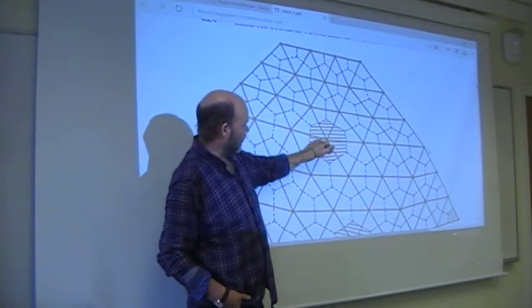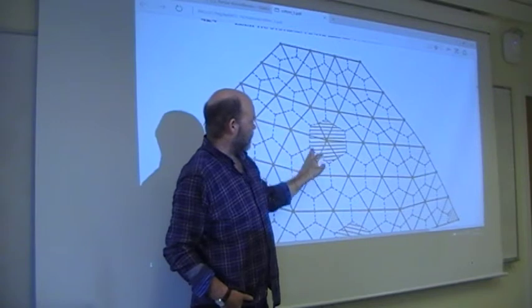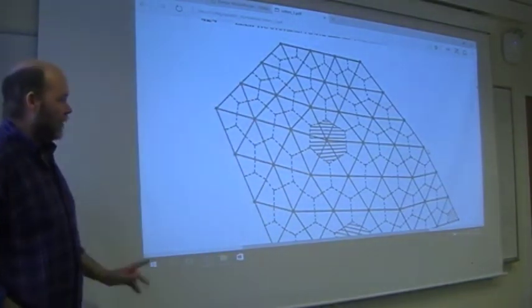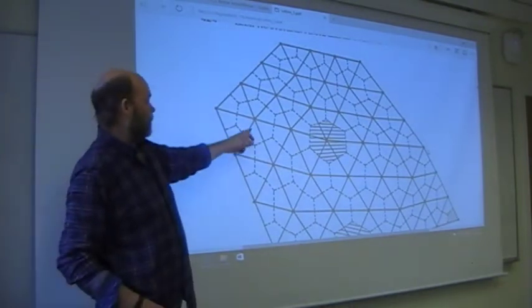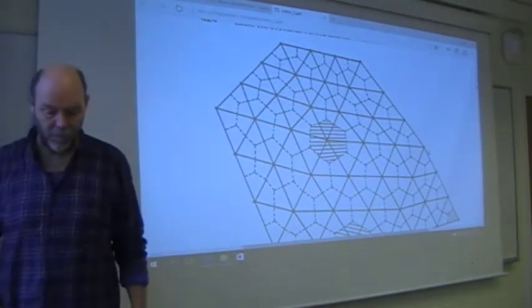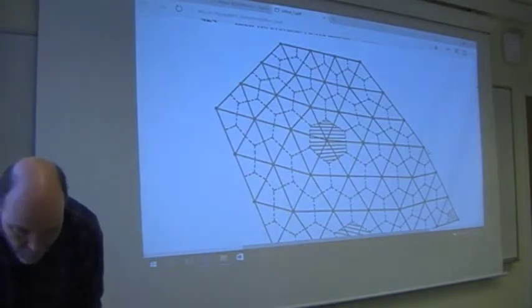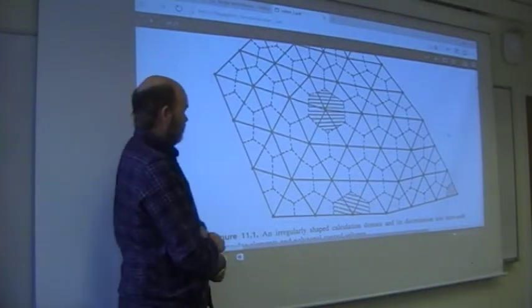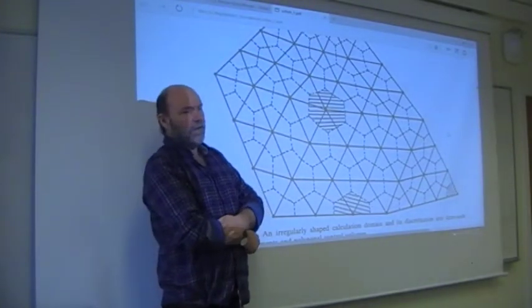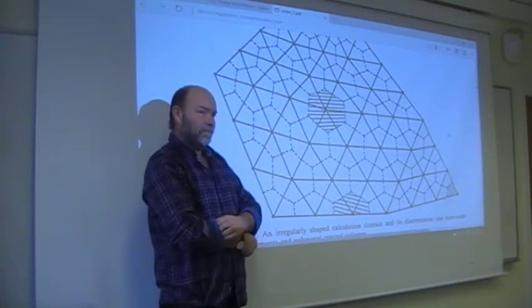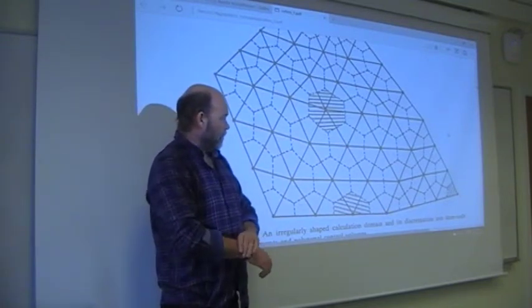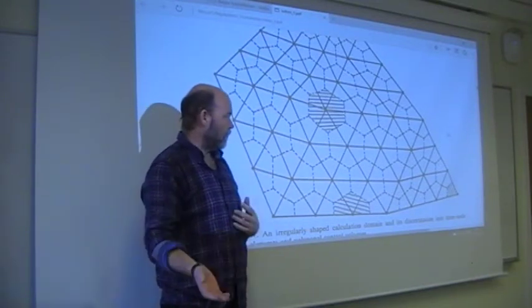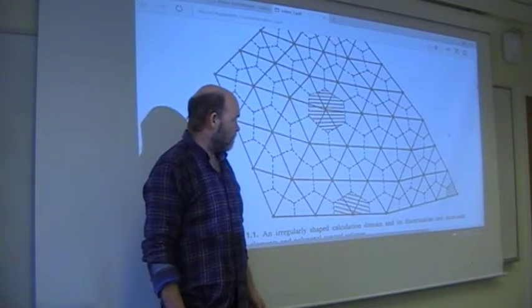Of course, you can be tilted anyway with these 6 triangles, but only linear variation then within one triangle. So I will call it finite volume. Using more advanced interpolation schemes, second order or sine waves or whatever, then I will call it finite element. But people still don't agree actually what is what. So the borderline between finite volume and finite element is not clear.